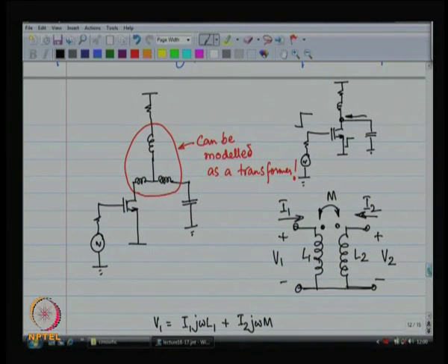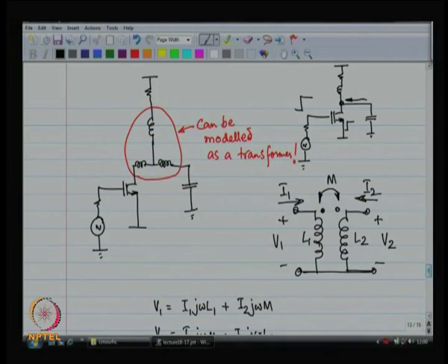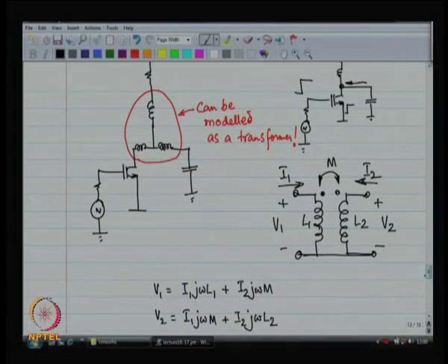You really have to sit with a circuit simulator, or you have to sit with pen and paper real hard, with probably some kind of software like Mathematica or MathCAD or something which can solve algebraic equations, and you have to work your way through the mathematics, and you will indeed see that you get significant bandwidth performance improvement. We also replaced the 3 inductors with a pair of mutually coupled inductors.